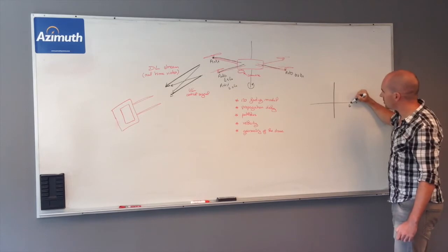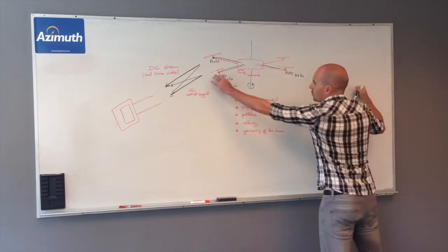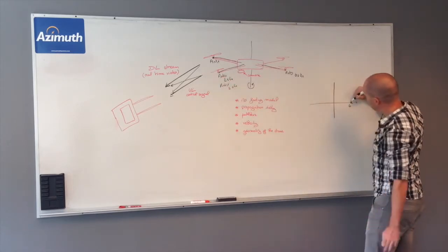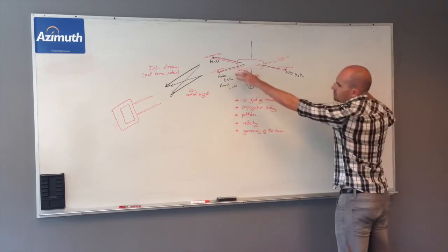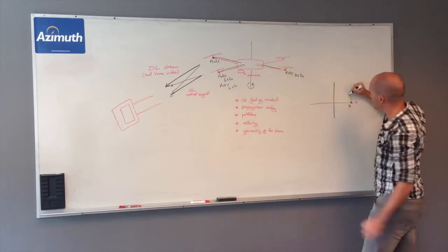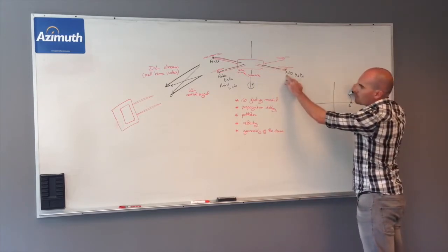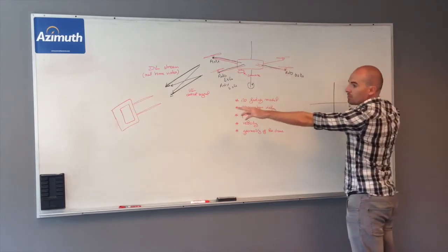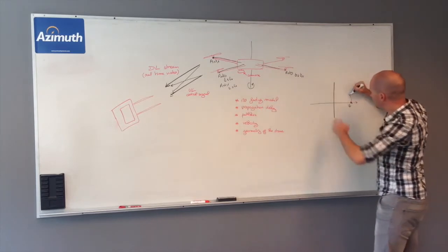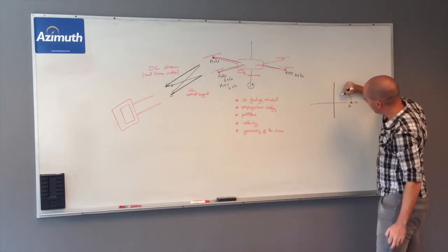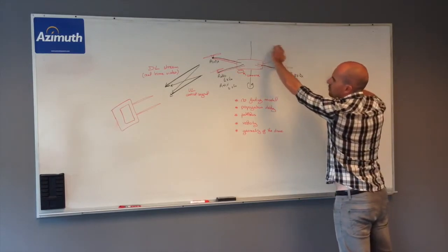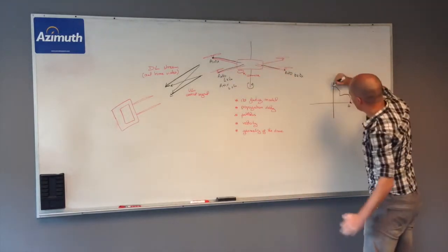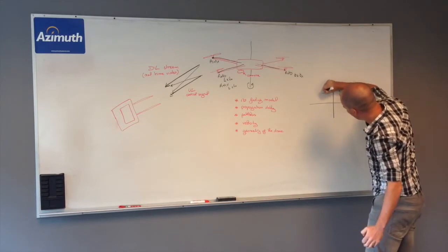Then the drone starts rotating, still has a pretty strong power, and at some point it would get hidden by the drone itself. So the power this antenna will receive from the controller will decrease. And when antenna 0 goes around and goes back to its initial position, then you will still have this strong signal.